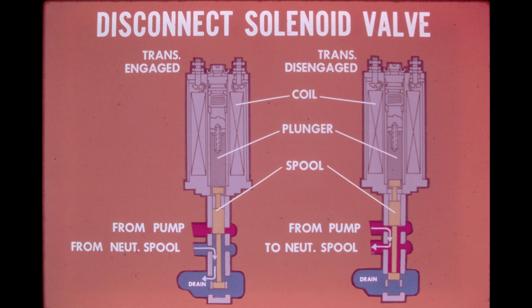When the spool is in the raised position, a flow of oil at system pressure off a cored passage from the back of the main regulator spool is directed to the neutralizer spool as described in the previous frame.